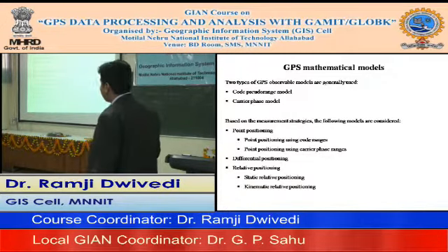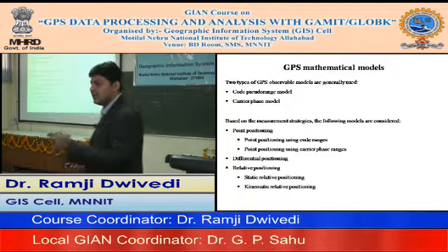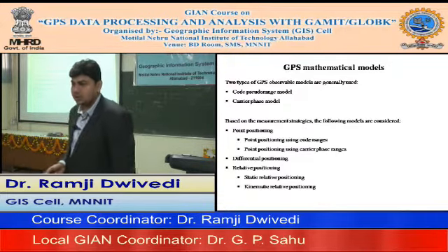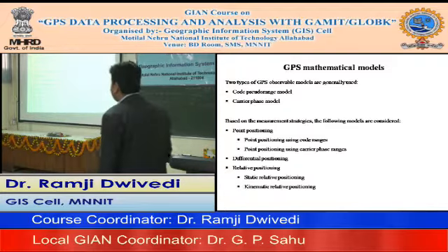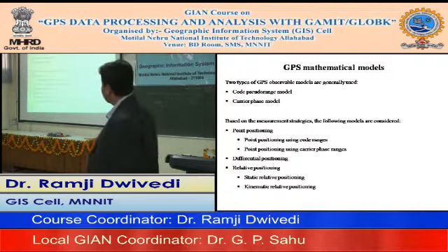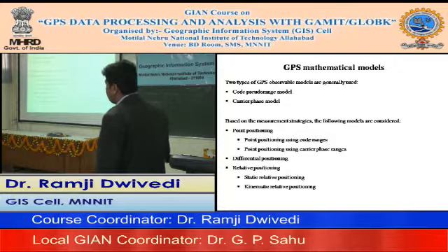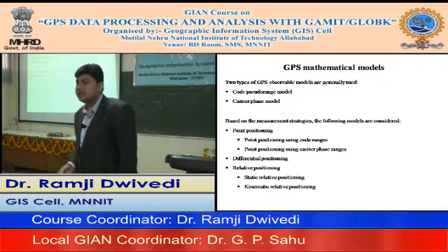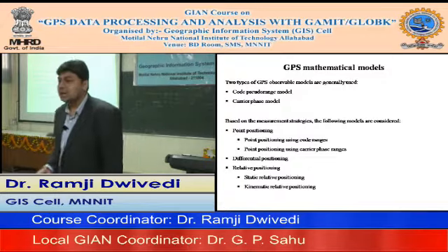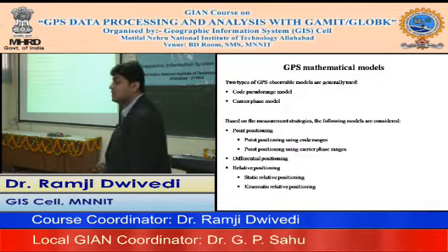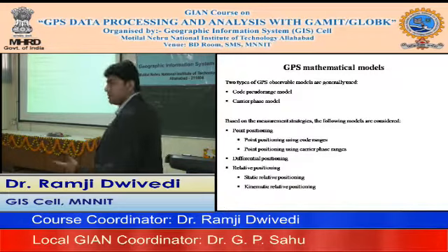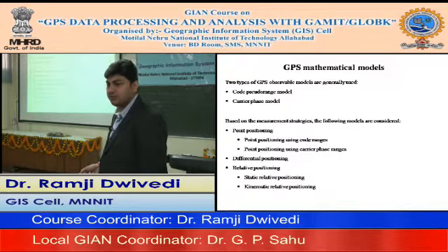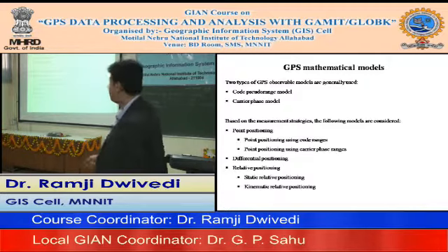So we'll start with point positioning. Simply you have a receiver and you want the point position with the help of the data acquired. So we'll see the point positioning using code ranges, code pseudo ranges I would say, and the point positioning using carrier phase. Another point is that we actually evolved, when selective availability was in place, how do you start what we call differential positioning, or DGPS. So the evolution of DGPS started when the selective availability was there, and nowadays it is helping us to achieve a little more accurate information with the help of code pseudo ranges.